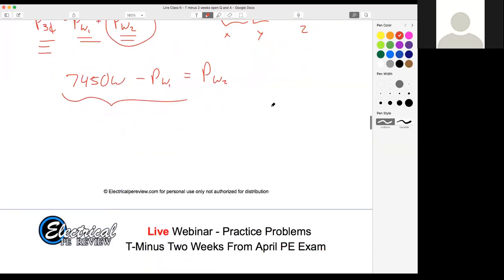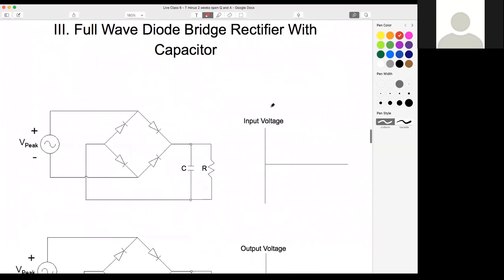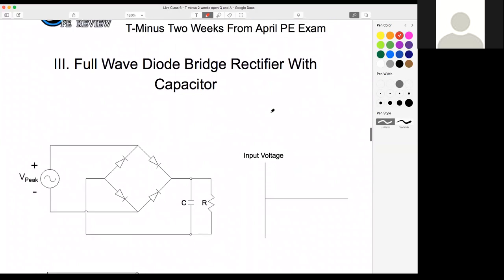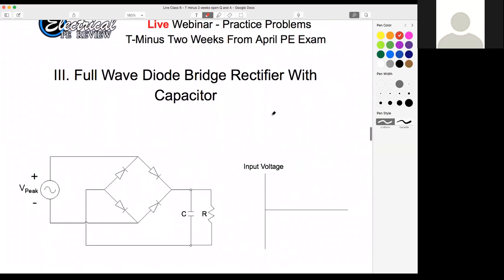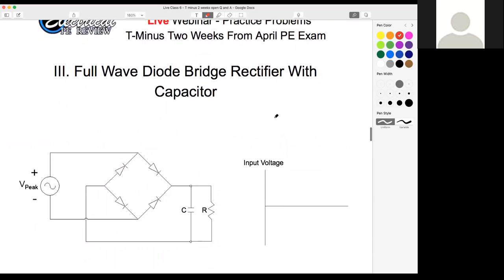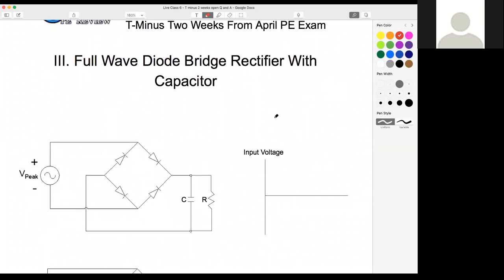All right, moving on. Look at this one right here. Keen has said if power factor equals 1, does it mean max power? Keen, if power factor equals 1, that means we have a purely resistive load. In other words, if our power factor is 1, then our power in watts equals our power in volt amps, and we have no reactive power.